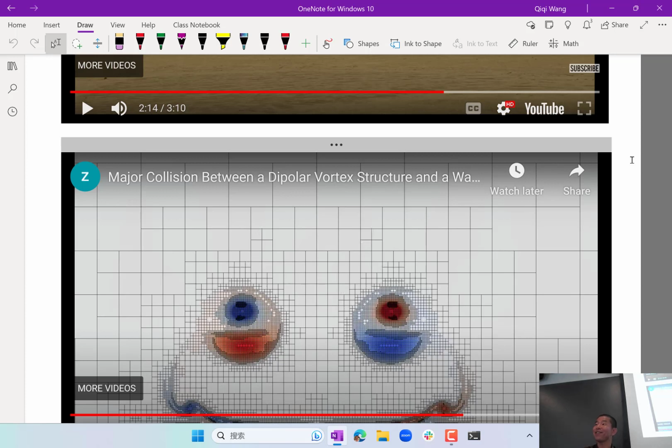It's the velocity squared. That is why the induced drag for an airplane that generates only a little bit of lift is negligible. But the more lift it generates, the induced drag goes like the square of the lift. It's exactly because of the relation between momentum and kinetic energy behind the airplane.